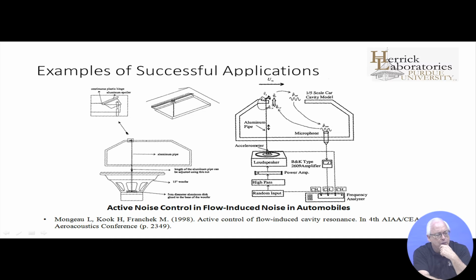And perhaps you've had this experience where there's vortex shedding over the sunroof that then locks into an acoustic mode in the vehicle interior and produces very strong pulsations in the passenger space, which can be quite uncomfortable.